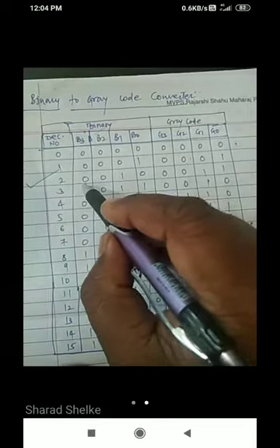What is the actual process to convert a binary number into gray code? I will explain it by taking a single example. Suppose the number is 0010, and see how its gray code is converted. All of you know the procedure. Keep the first digit as it is, then add the first two digits, that is 0 plus 0, we get 0. Add the next two digits, 0 plus 1, we get 1, and again add 1 plus 0, so we get 1. So the gray code equivalent of the binary number 0010 is 0011.